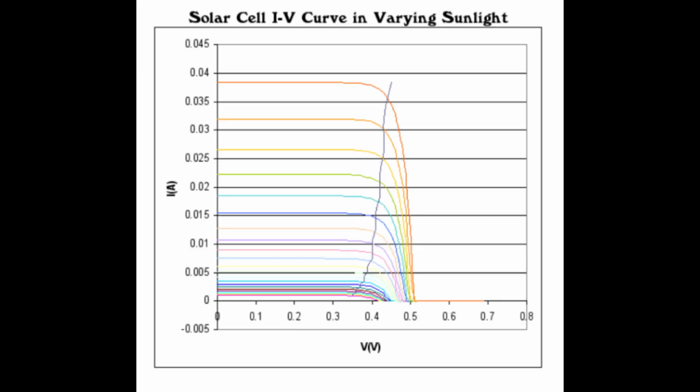Now I want to talk about making solar panels work together with maximum efficiency. For the Northern Hemisphere, an ideal static solar installation is one with all panels facing south and tilted at an optimal angle. The angle depends on latitude, and there should be no shading. All the identical panels want to receive the same illumination. Unfortunately, this may not be practical for all installations.